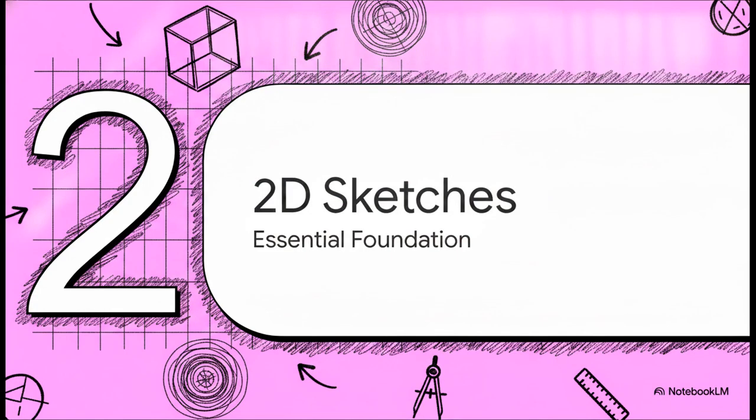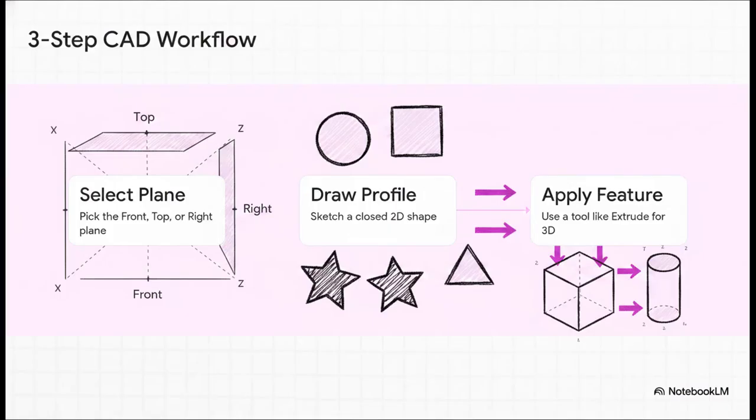Moving right along to mastering 2D sketches. Look, you literally cannot have a 3D model without a solid 2D wireframe blueprint. It is the essential foundation of any CAD workflow. Every single design you'll ever make here starts with this exact same 3-step workflow. First up, select a plane, grounding your concept onto a mathematical X, Y, or Z plane. Second, draw a closed 2D profile like a circle or rectangle. And third, apply a feature to just pop that sketch right into 3D.